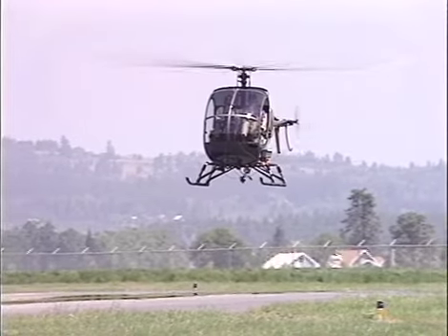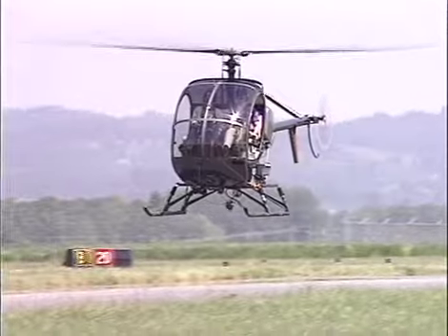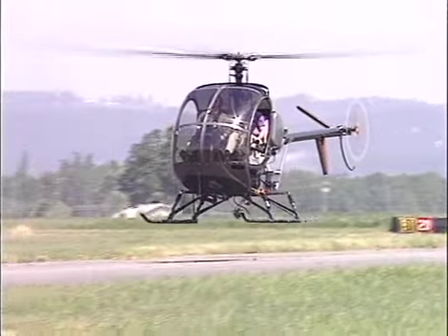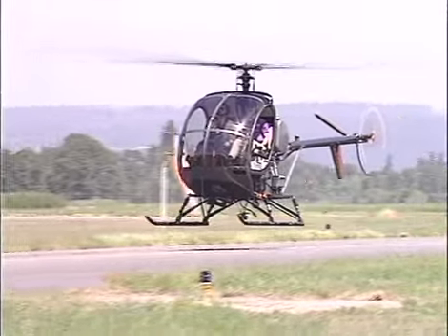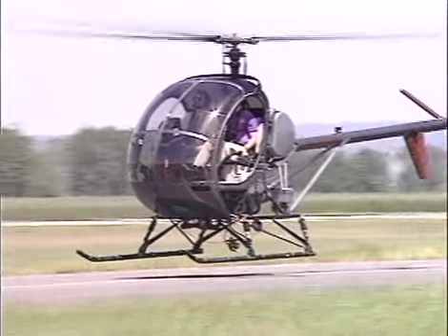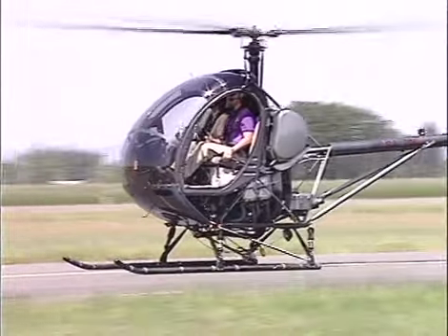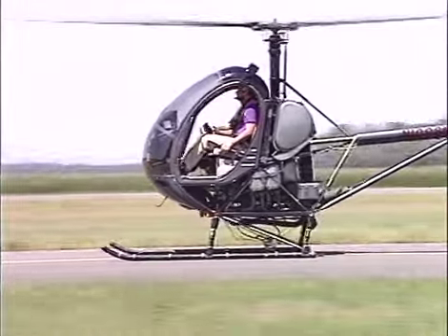The approach to a running landing is shallower than normal to take advantage of ground effect and effective translational lift until surface contact is made. Upon entering ground effect, maintain a level attitude and allow the airspeed to bleed off. As the aircraft settles to the surface, press the cyclic slightly forward of neutral to tilt the rotor disc away from the tail boom. Control direction of movement with the cyclic and heading with the anti-torque pedals.